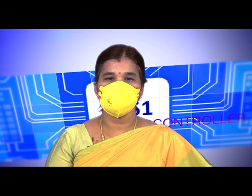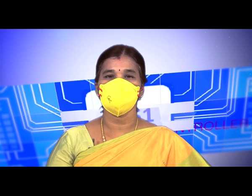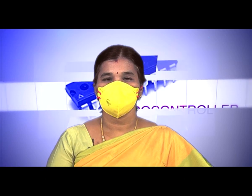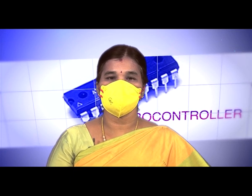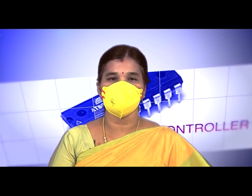Before starting the design, we have to know the internal structure of the controller. So, in today's session we will discuss the 8051 architecture. The 8051 is an 8-bit microcontroller which acts as the CPU, as in a microprocessor, used for ALU, arithmetic and logical operations. Most computers are developed based on the microprocessor, and most embedded systems are developed based on the microcontroller.